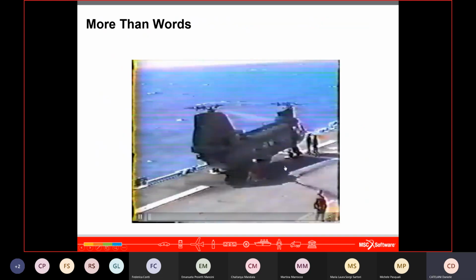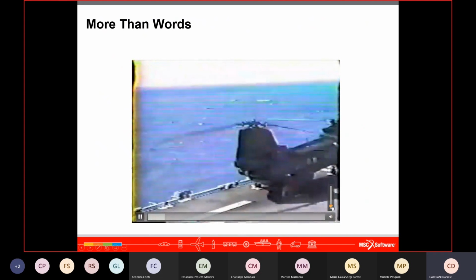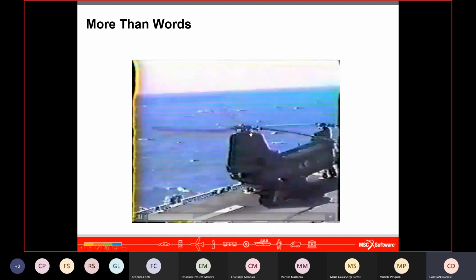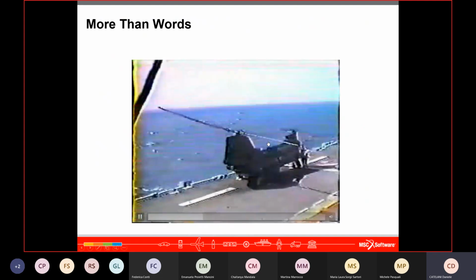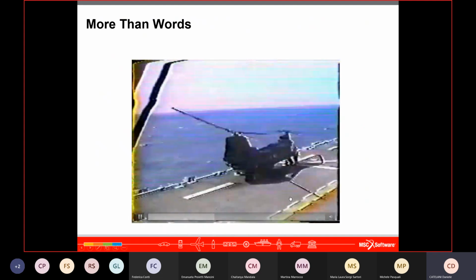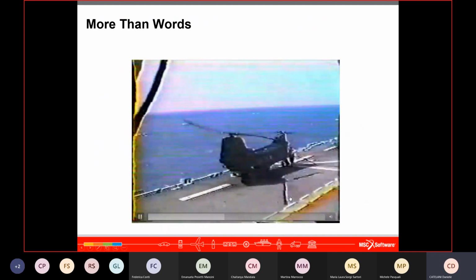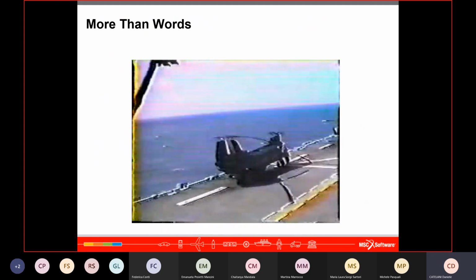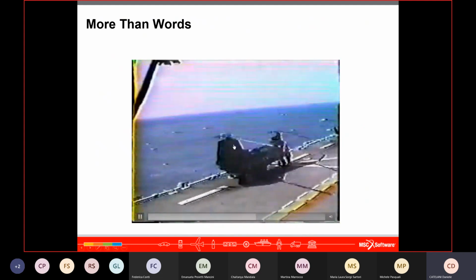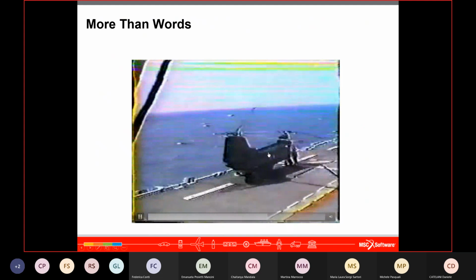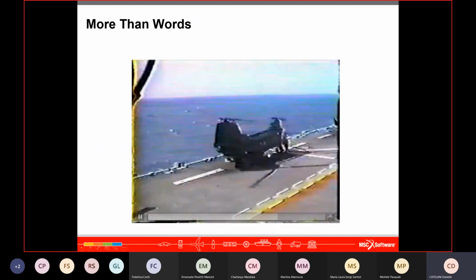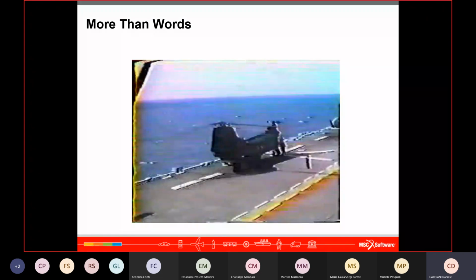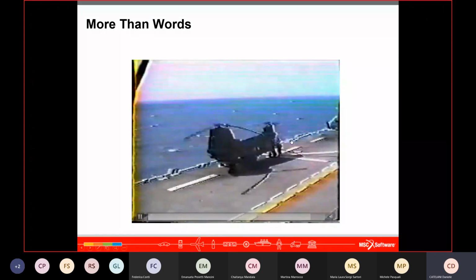When the helicopter is on the carrier ship, the pilot ramps down the engine and the helicopter rotor starts to slow down. You can have an unlucky situation in which an aeroelastic combination between the aerodynamic forces and the structural characteristics of the blade pushes the rotor to move in an abnormal way outside of the rotor plane.